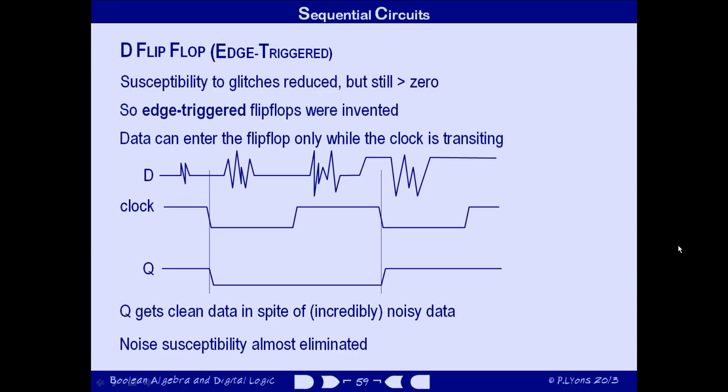The particular flavour that we've drawn here triggers a load when the clock signal is changing from a high voltage to a low voltage, and is called a falling edge triggered flip-flop. Rising edge triggered flip-flops can also be constructed.